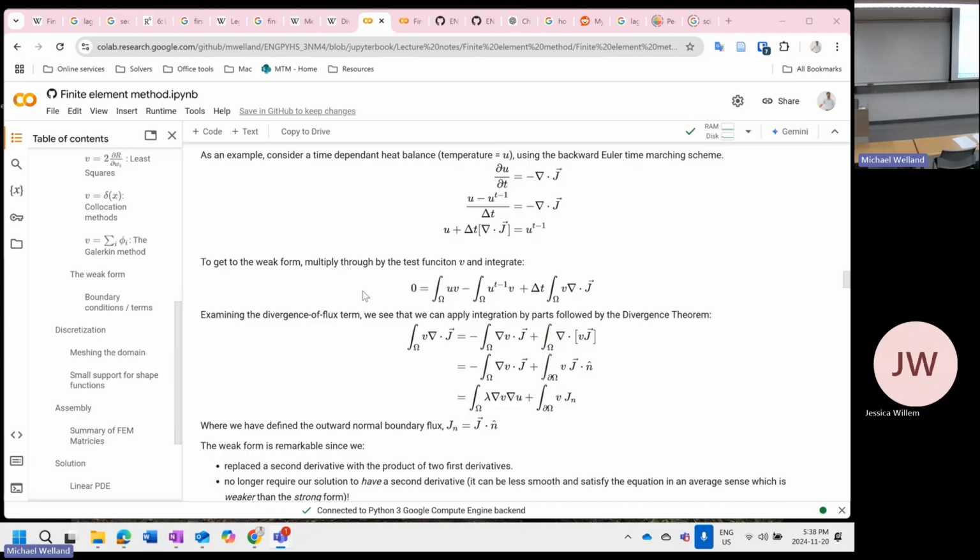Okay. To get the weak form, if you're using something like COMSOL or ANSYS or Abaqus, and I suspect FlexPDE, you don't need to know how to use the weak form. You don't need to convert it. If you're using something like FEniCS or Firedrake, you are going to have to use the weak form, but luckily there are a lot of examples, and to be honest, it's not that hard.